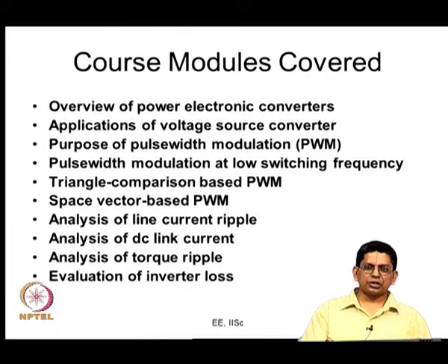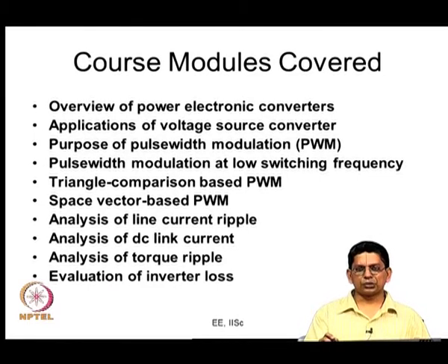In all these applications, the voltage source converter has three things: one is the DC voltage, another is the modulation, and then the AC voltage. These three are mutually related. The modulation determines the efficiency, which you are particularly worried about. The modulation also determines things like waveform quality. When you do a DC-AC conversion, you are not producing a sinusoid, you are producing a waveform with a lot of harmonics.